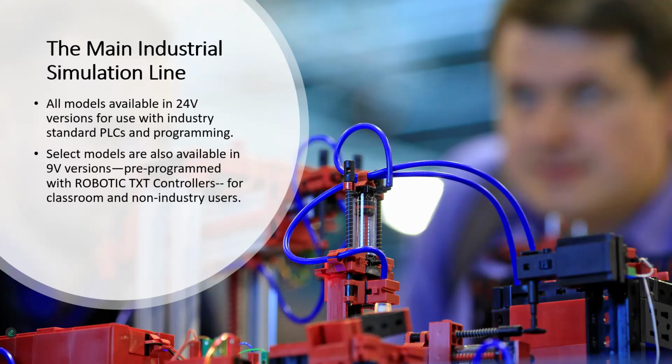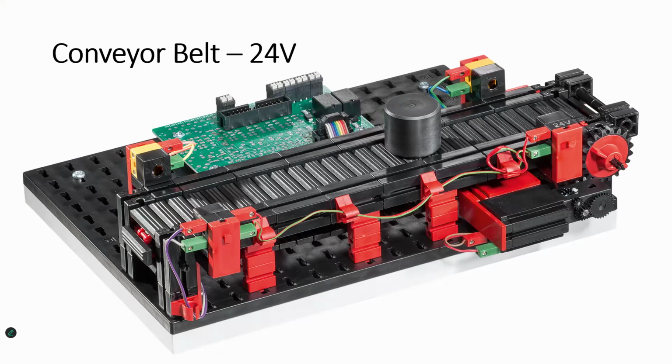This is essentially a transport belt with a length of 275 millimeters that's used to transport workpieces with a diameter of up to 29 millimeters. Multiple conveyors can easily be connected to increase the length of transport as you might desire. Components on this model include an XS motor, a push-button limit switch, 2 phototransistors, and 2 LED light barriers. The dimensions are approximately 14 by 10 by 4 inches, and it weighs just about 2 pounds. The model is currently available in a 24 volt version with a multi-pin connector, which is 26 pins in a 2.54 millimeter grid, as you see here.